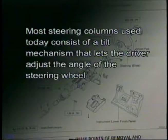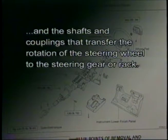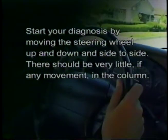Most steering columns used today consist of a tilt mechanism that lets the driver adjust the angle of the steering wheel, and the shafts and couplings that transfer the rotation of the steering wheel to the steering gear or rack. Start your diagnosis by moving the steering wheel up and down and side to side. There should be very little, if any, movement in the column.